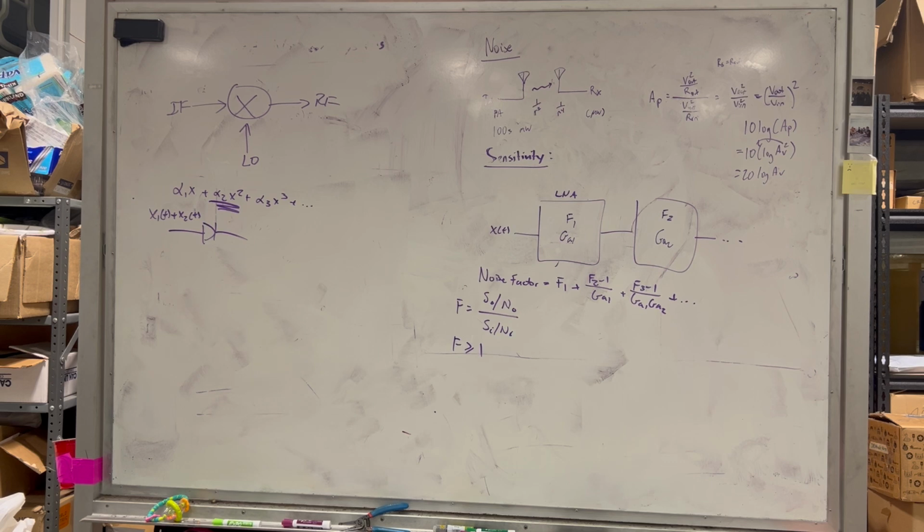If IF is super nonlinear, that's your carrier, right? You're messing up the information on it, right? Potentially, yeah. You don't want to mess that up. And then the LO, we're filtering it anyway, so if it is distorted, you're more okay with that. Well, no, it's because of this: